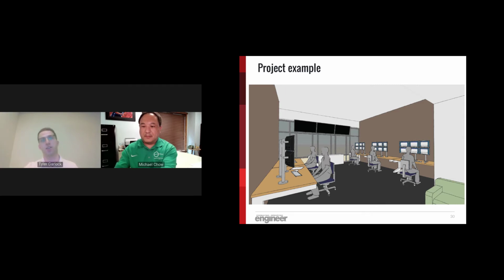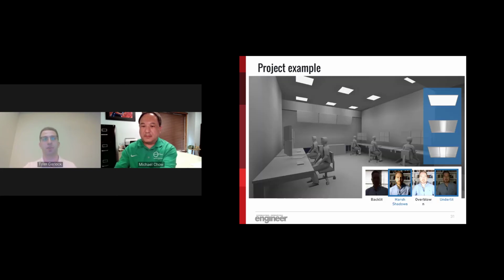So that became very clear that downlights were probably not the best option going forward. So then we considered doing something more like a 2x2 lay-in troffer. These troffers are good because you can get direct-indirect troffers that give you a little bit softer lighting, and indirect lighting that bounces around, so it can fill in some of the shadows. It also has good side-to-side distribution, so you get some reflection off of those vertical surfaces behind the screens.